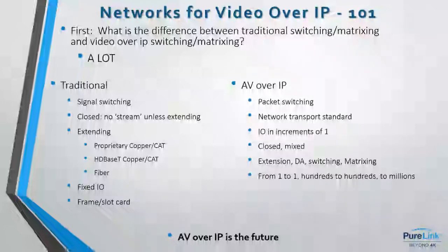flexibility, expandability, serviceability. Think about if you have one channel fail on a fixed switch, an 8x8, and one channel's not working, input or output. You have to pull it. You have to unwire that whole thing, disable 8 displays, 8 sources, and that's not the case in AV over IP. You just pull whatever one piece is the issue.